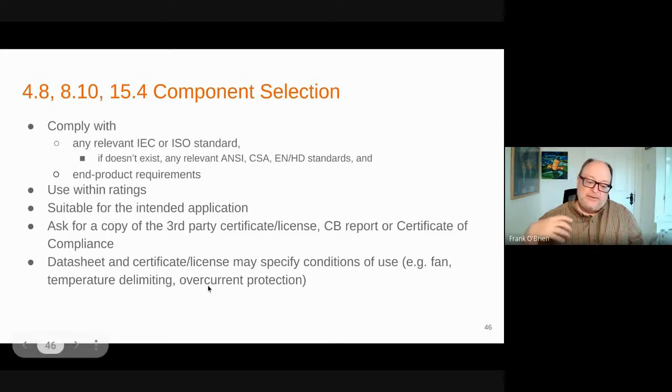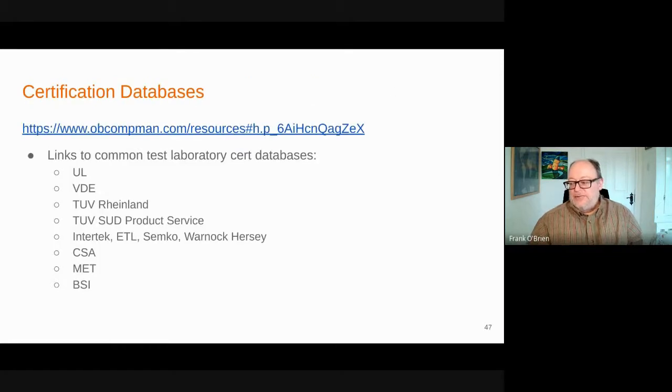You can go to third-party certification databases and find those things. And in the case of a power supply, you're probably going to want the test report, not just the certificate. So this is a link to my website, and some of these links could be dead. I haven't used them in a while. But in my day-to-day, I would visit these sites. And so I put the links on a public page. But they have searchable databases of components, so you can kind of independently verify what a data sheet says.